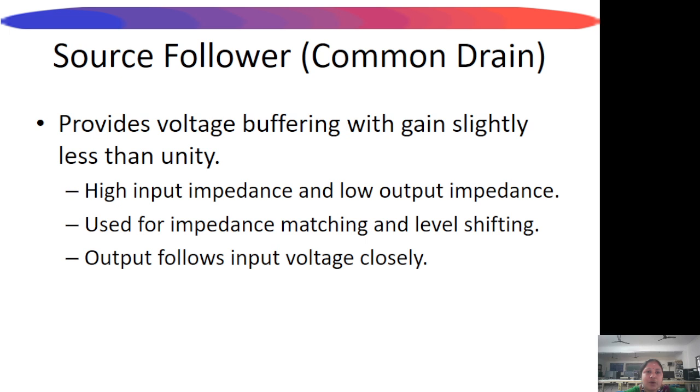It also provides low output impedance. This makes it suitable for impedance matching. The output voltage closely follows the input voltage. Source followers are commonly used as buffers. They prevent loading effects between stages. This configuration improves signal integrity.